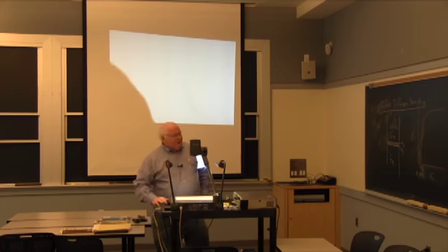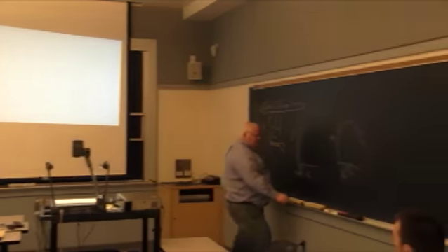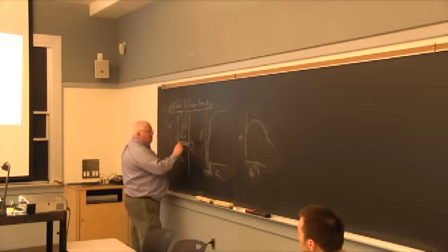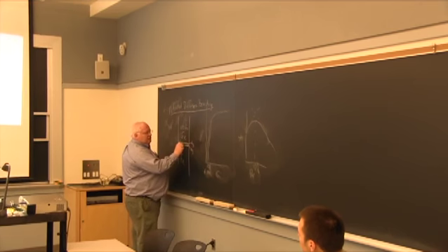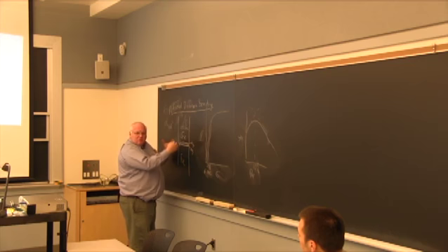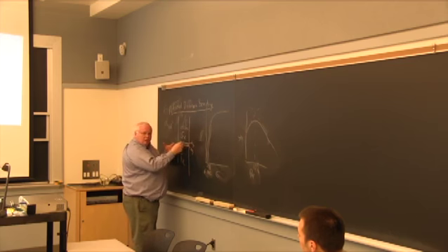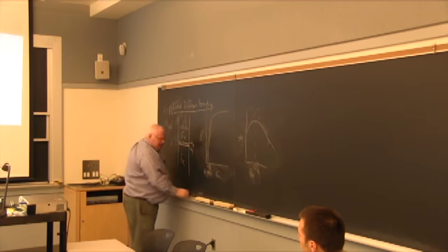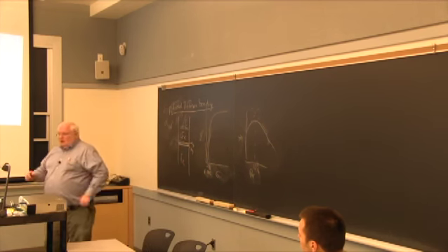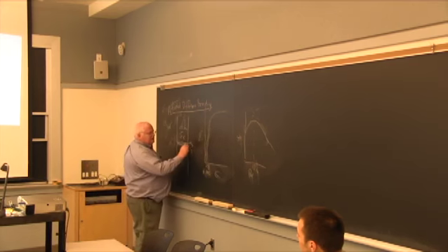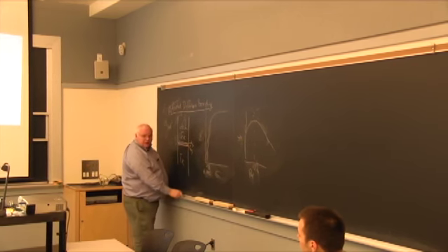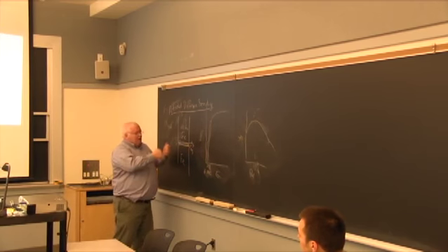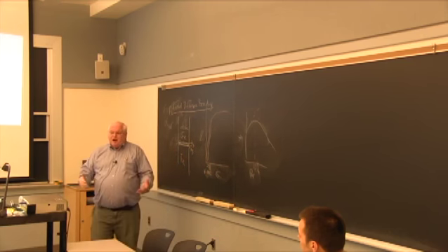in very thin joints. And basically, when I say triaxial state of stress, just to give you a little bit, because I didn't prepare to go through the whole thing today, but this is an unyielding surface. The iron is unyielding. This stuff wants to suck in, if you want to think of Poisson's ratio or whatever. It wants, as you're pulling on it, it wants to pull in. It can't pull in because it's connected to an unyielding surface. And so that means it has an effective stress pulling it out this way, and you basically go with tension in this direction and biaxial tension in the plane, and that's a state of triaxial tension.